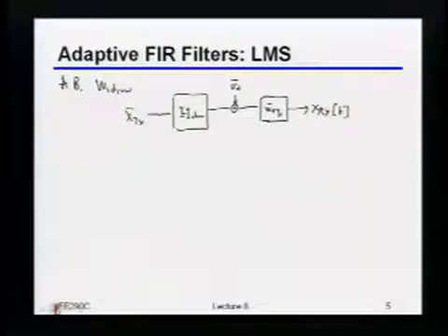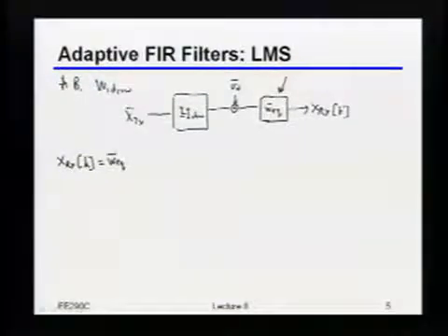So to see how we can figure out how to adapt that equalizer, whose coefficients will just be the entries in this W vector, let's take a look at what it is that I actually receive. In other words, what is that actually comprised of? As should hopefully be clear from the diagram, the analog voltage that I'm receiving is essentially I take my equalizer, do a transpose, because you can think of it as doing a convolution.